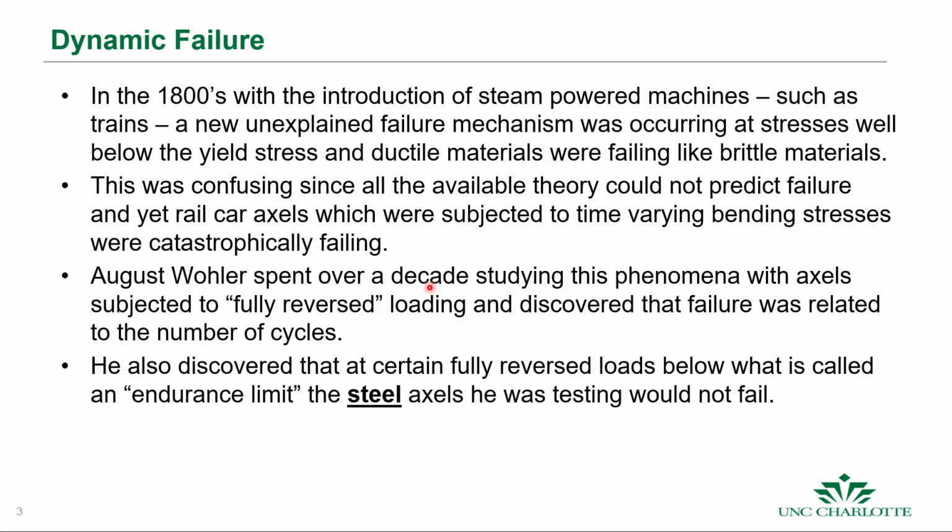And that's where we first discovered this concept of an endurance limit of a material. If you keep those cyclical loads below this endurance limit, which is a stress, then the materials will survive dynamic loading indefinitely, as far as we know.